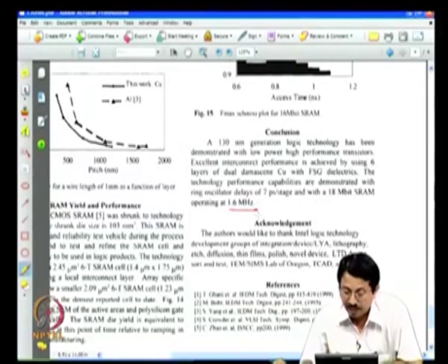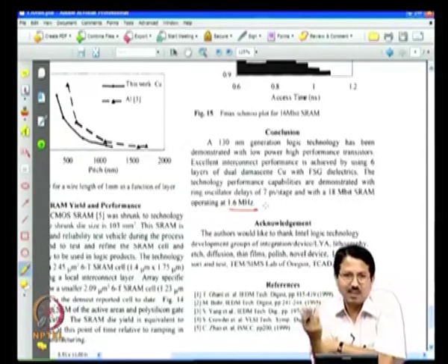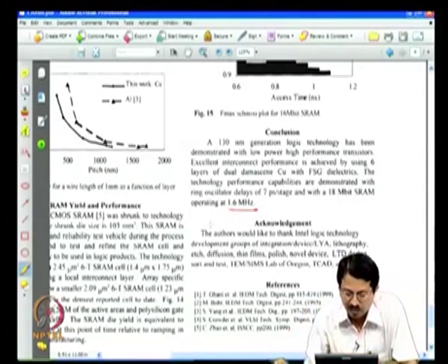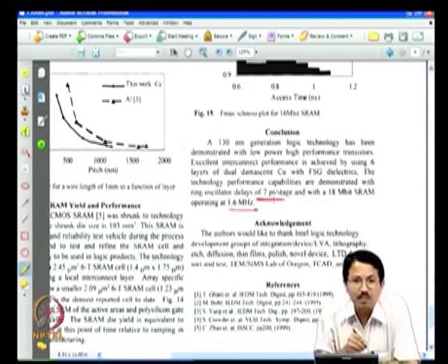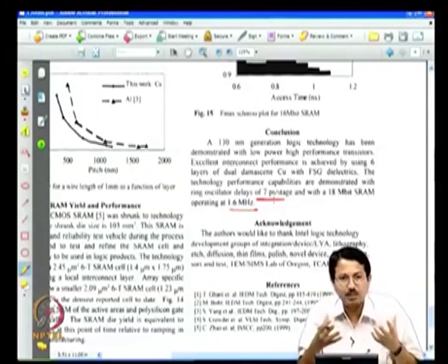So, actually it is not very clear here, I take back what I said. The previous one was a lower density SRAM, at 900 megahertz, but this is a higher density SRAM that is operating at a little lower frequency. As you start increasing the density, there is also an impact on the speed of the SRAM that you can build. Whereas the ring oscillators obviously are much more efficient, the basic technology is much better.